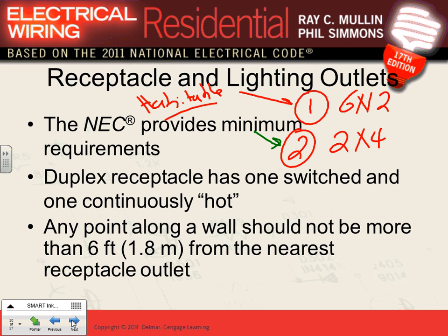2 by 4 is for the countertop of the kitchen. Everybody knows a kitchen countertop, right? You start from one edge of the countertop and measure: 2 feet, put a receptacle, then 4 feet, 4 feet, 4 feet. Here's the sink. Make sure you're not further than 2 feet away from the sink. Done. Either way, you're going to balance them. You guys are designers, so you're not going to stick to 2 feet; you'll use this as a guide and go a little bit more. If you're very close, stick in one receptacle. These are guidelines, the bare minimum.